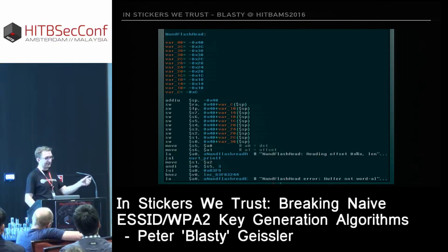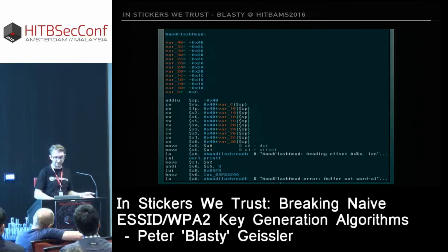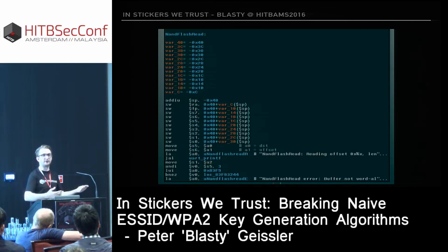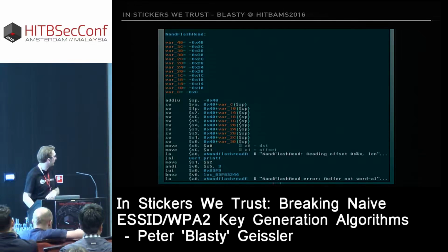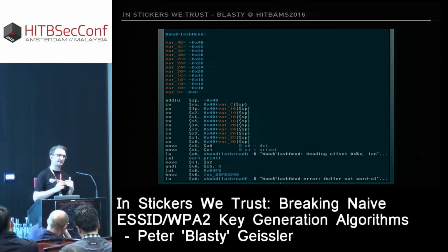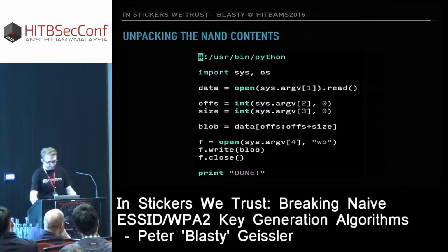If you launch screen with a device to a serial port, you can specify a baud rate behind it, so you don't have to use stty or anything. It's really great. And you can set screen up to do logging. So whenever any data is coming into your screen, it will write it to a log file, right? So I had this really hacky, weird thingy, and I set it up. I left it run overnight. A good night of sleep. And when I came back, I parsed the log file, I grabbed out all the ASCII hex, and I turned it into a binary file. So I had a dump of the NAND.